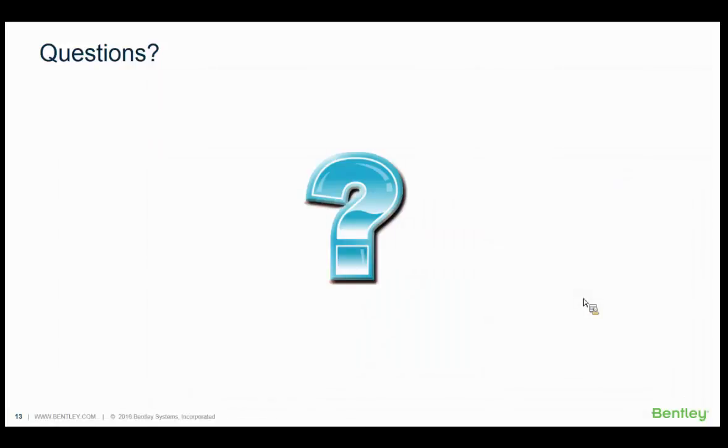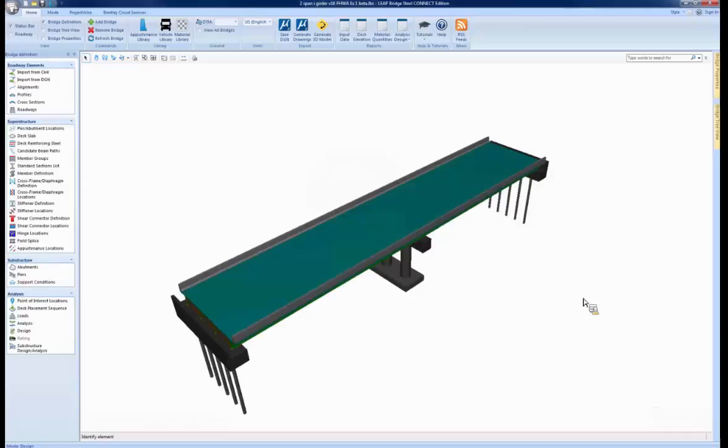Hi, Steve. There's a question here. Does the optimization use one fixed size for the entire length of the beam? No, actually it doesn't. The optimization reports the required flange size for each POI based on the smallest area that either meets the code requirements, or number two, reaches some limit specified by the user.